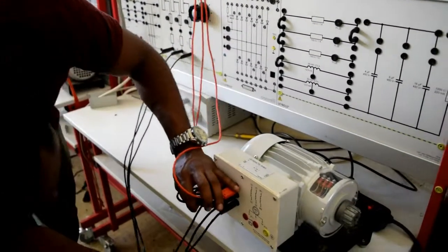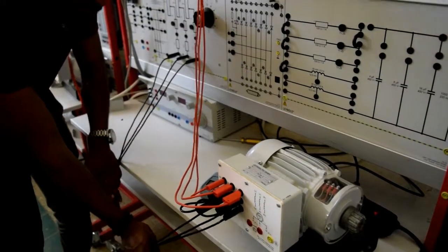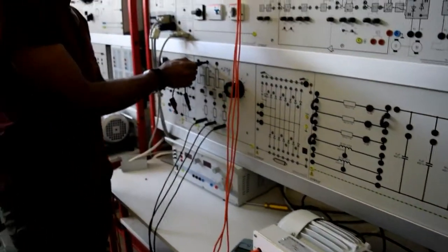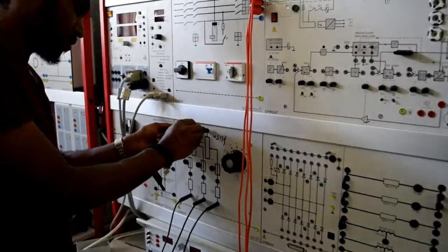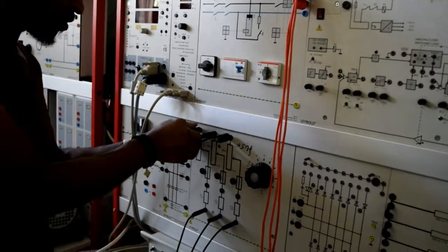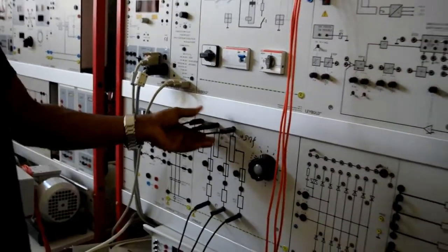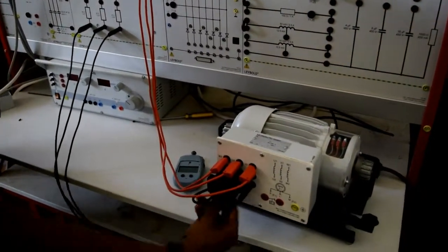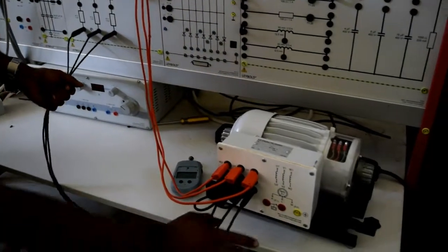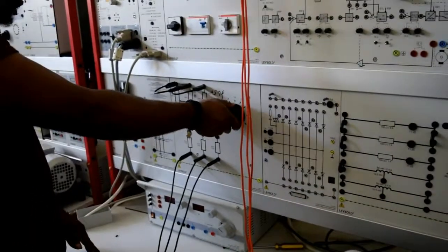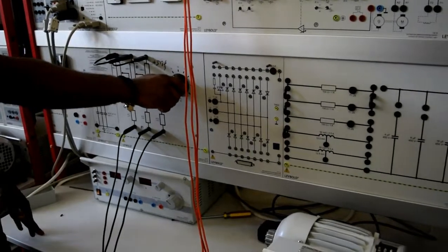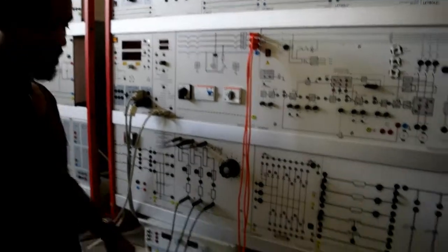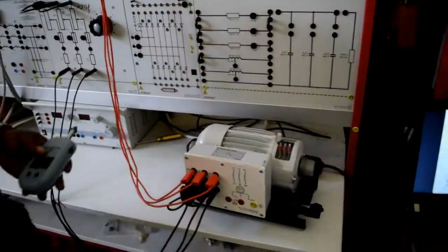That means the rotor resistance goes to the slip rings. As I said before, the advantage of phase wound over the squirrel cage one is that we can add additional resistance to the slip ring. So I connect additional resistance to the slip rings, then I make the resistance 100%, and then I start the motor. Now the motor starts. Then I will see the speed measurement.